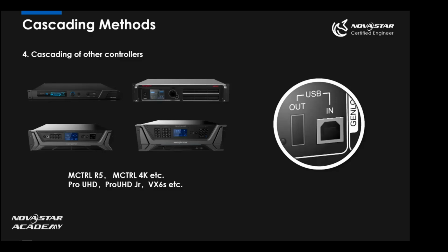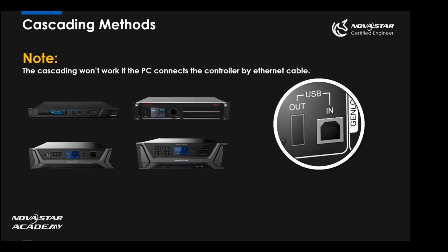The answer is no. If we use the Ethernet cable to connect the first device, but we connect the rest of the controllers by USB cable, it cannot work. So in this situation, if we want to connect multiple devices like this, we have to use USB cable only. So on this point, I think you'd better take care of this.